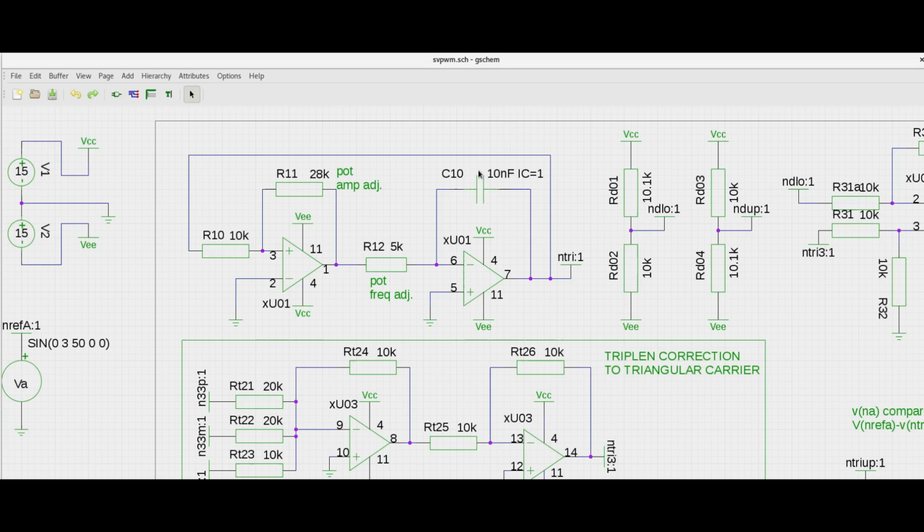Because of the capacitor, this will discharge, and this voltage is going down. Once it crosses the hysteresis lower trip point limit, this will go low, and again this will start rising because there is a change in the state here.